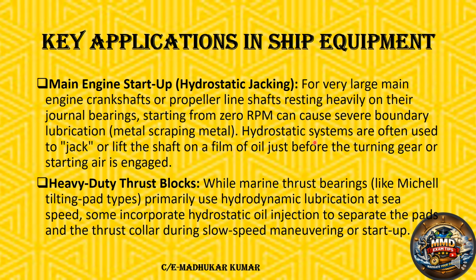So the hydrostatic system is basically used to jack up or lift the shaft due to the oil film between the shaft and the bearing. And then we turn the engine with the help of the turning gear. After that, we blow through the engines and all. That is a different part. But all these things help to maintain sufficient separation and avoid metal-to-metal contact.